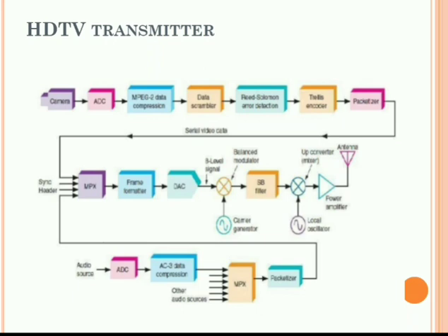This signal amplitude modulates the carrier. Whatever the signal we have, we are using amplitude modulation here. We are suppressing the carrier. We are using one sideband, upper or lower, of the particular modulating signal, and a vestige of the other sideband, and in that form we are transmitting the signal, resulting in symbols.